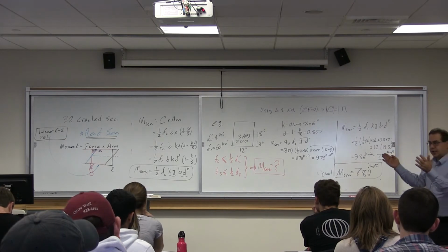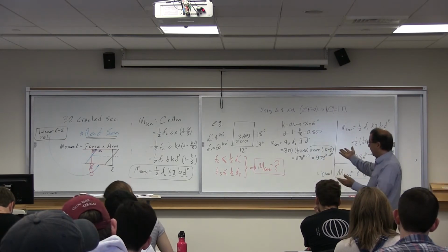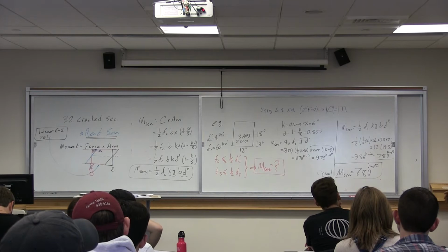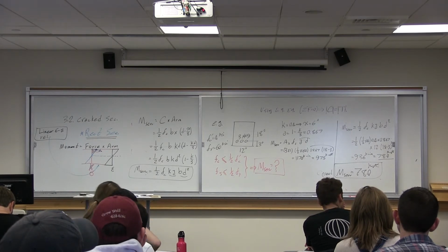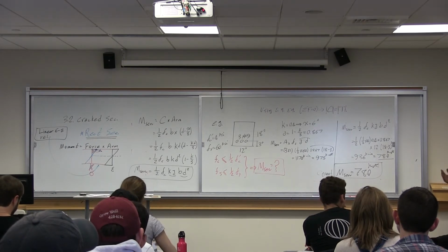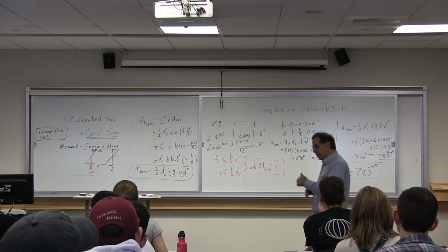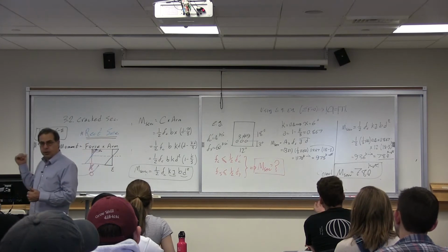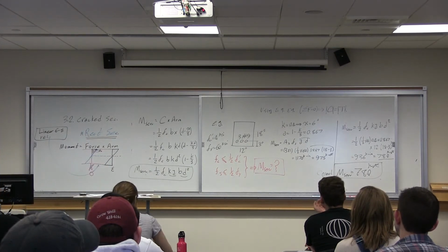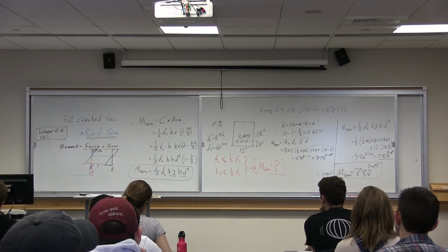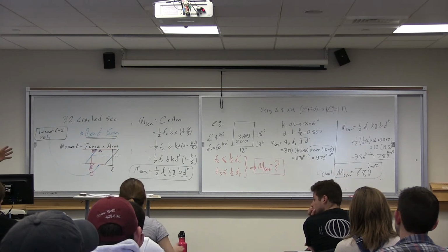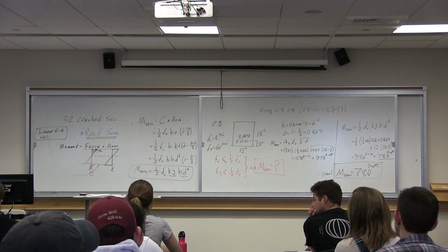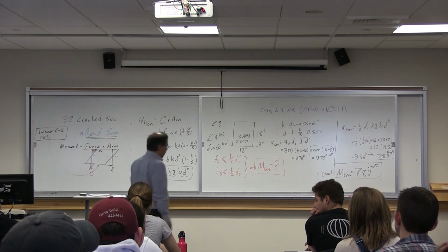More often we use rectangular sections, and if that's the case, use of this method is the easiest approach to solve the problem. Alternatively, if your section is not rectangular, which this cannot be used, or you would rather use the moment of inertia, you can solve this problem using moment of inertia. That's a different method of solving it. This is one method. Now let's talk about the second method.